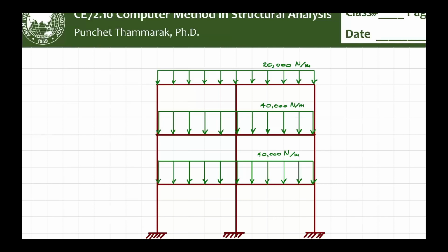So when you design, maybe you put the specification for the roof slab. I personally, if I construct my house, I put high strength concrete there. High strength concrete, low permeability, low pore, because you don't have much excess water from your mix. Well, it is difficult to pour, of course, but what's wrong with that? It is just a slab, it is not a beam.